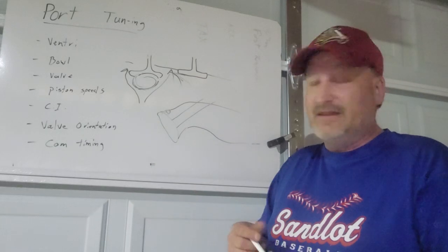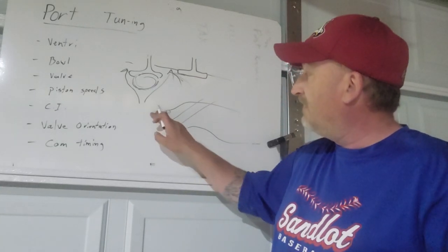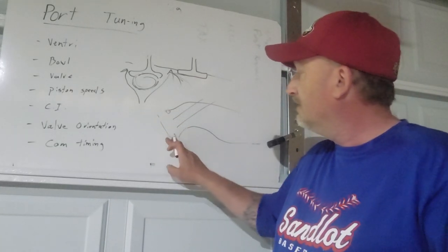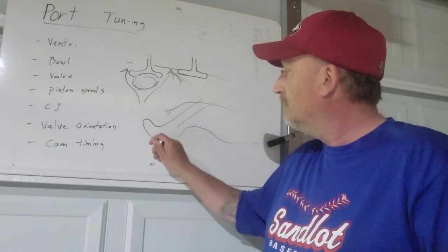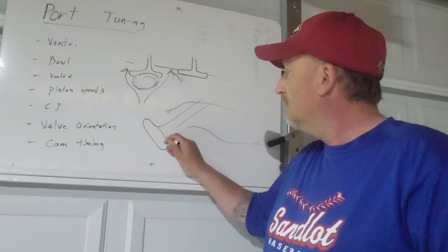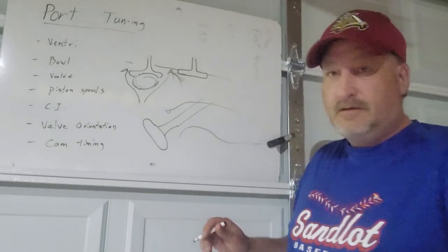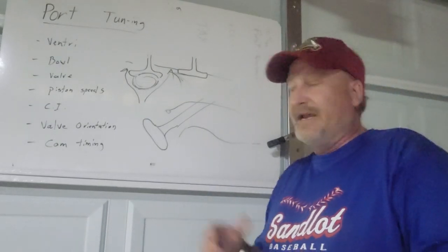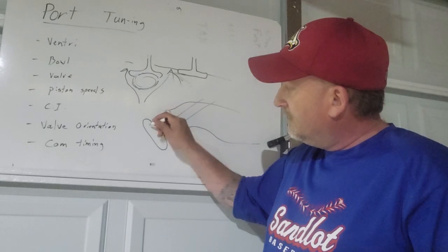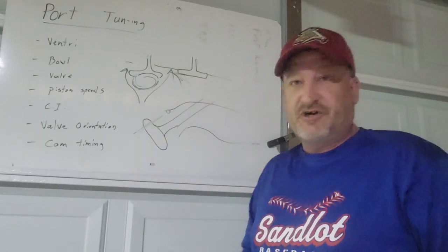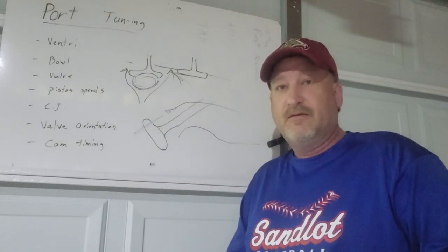If they keep it within line, say the valve is now open, if the air is moving straight to the angle of the valve itself, the valve becomes a restriction to the airflow path.